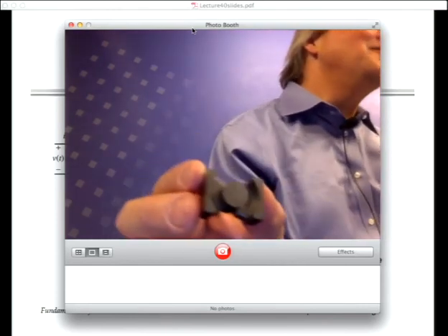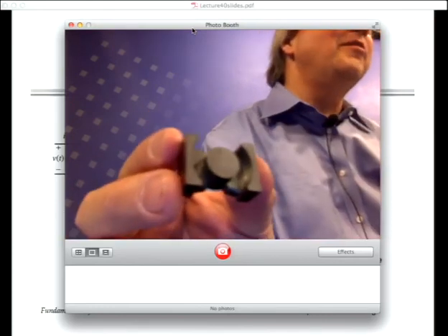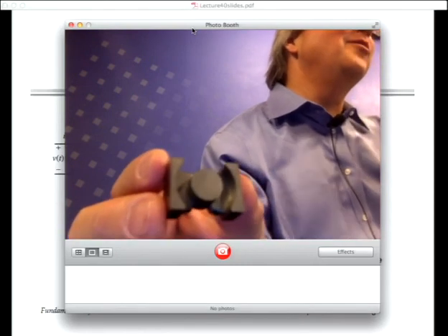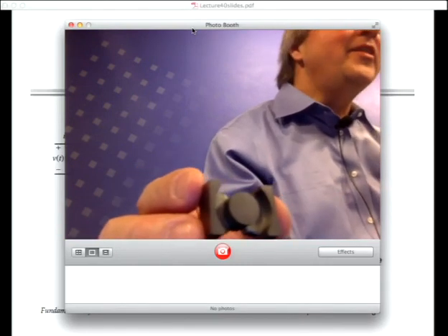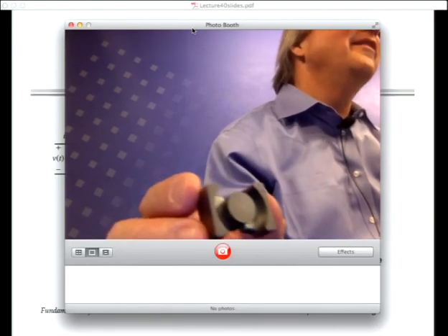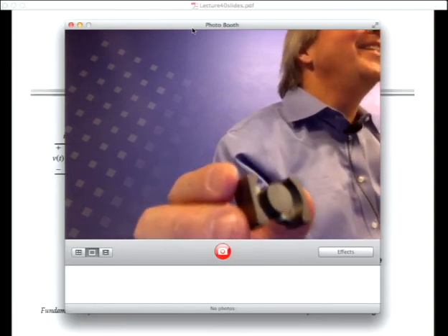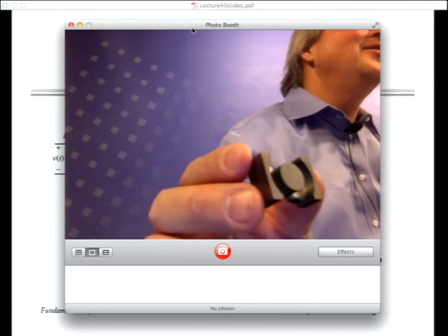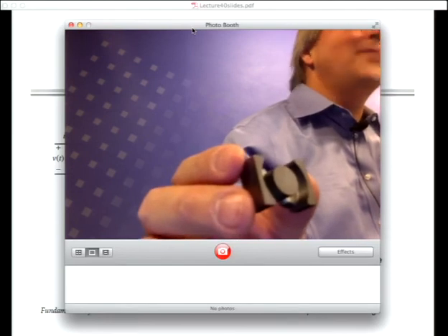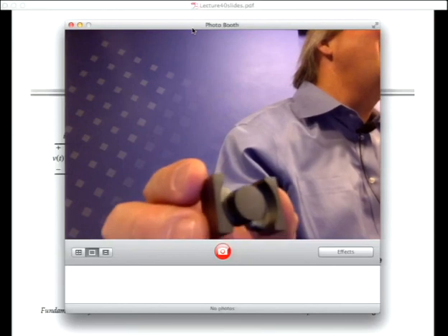It's actually not always true. For example, in this shape of core, they may decide that they need to make the outer legs thicker just for mechanical reasons. And so then the flux density will be different at different points going around the core. On the data sheets, the manufacturers give you a number that they call the effective cross-sectional area. And exactly what that means is hard to say. Maybe it's the smallest, or maybe it's some number that when you plug that in to calculate the core loss, the number comes out right. Probably not, though. But you do what you can, what you have to.